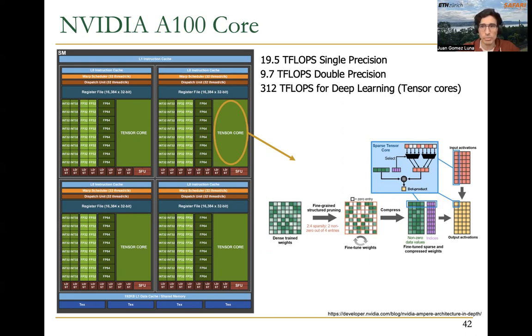Another important commonality between this A100 core and the traditional view of SIMD processors is that this one also uses banked memories, and this shared memory here is a banked or interleaved memory, in order to be able to sustain multiple accesses to multiple elements that are going to be used by the corresponding SIMD units that we have in GPUs.